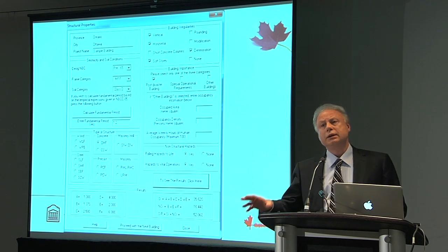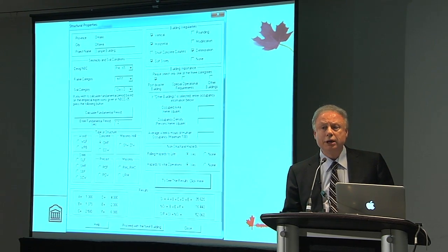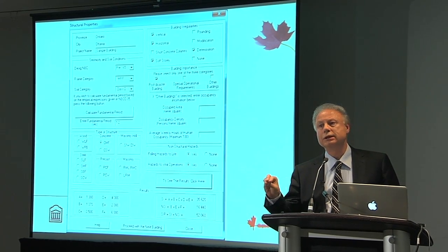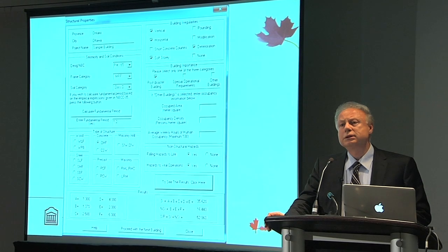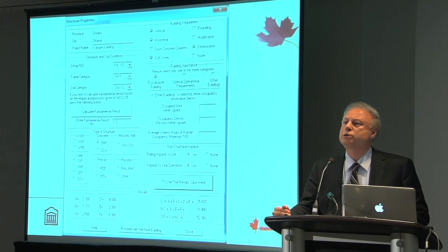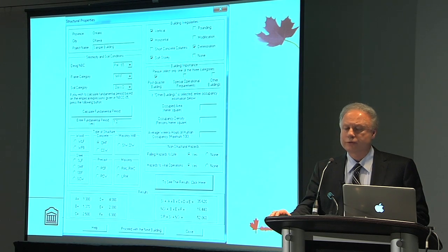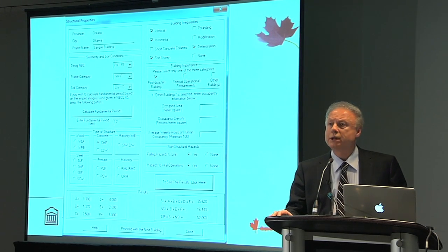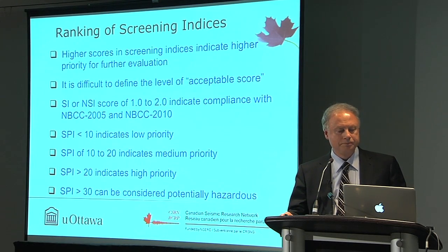Now this is done in the recent edition through software. It's a simple software. You can do a specific building analysis. Because it's a function of period, we did not expect the technical people who are going through the screening process to calculate building period, and hence there's this little tool provided in the form of an Excel program that calculates building period and associated vulnerability factors.